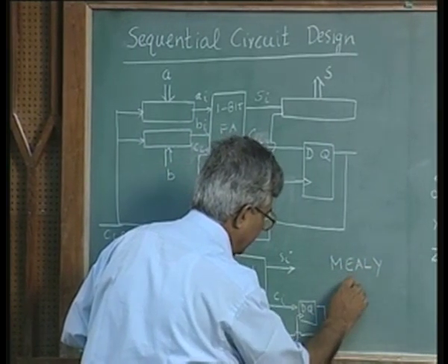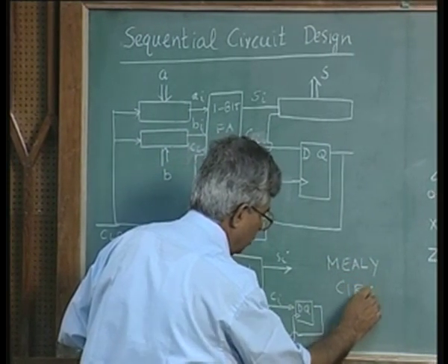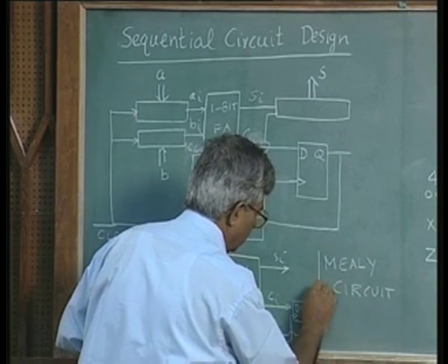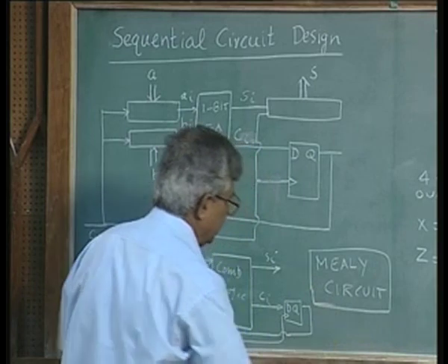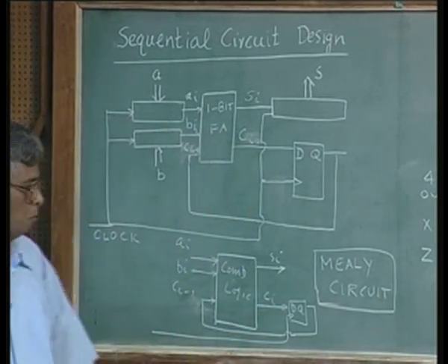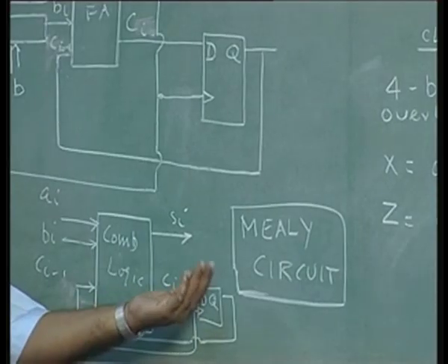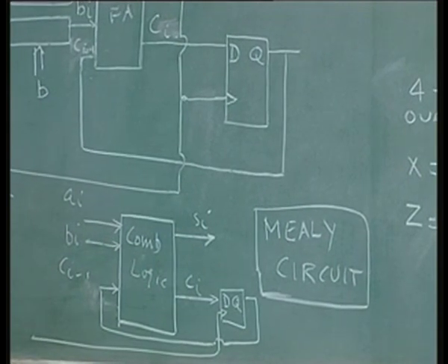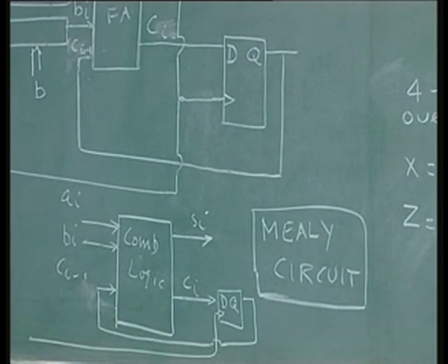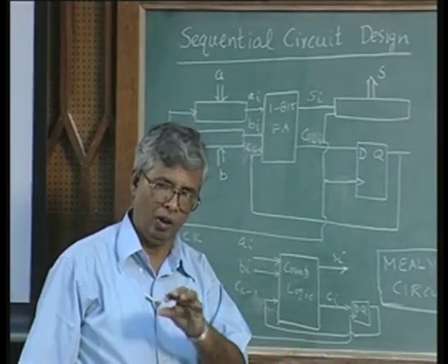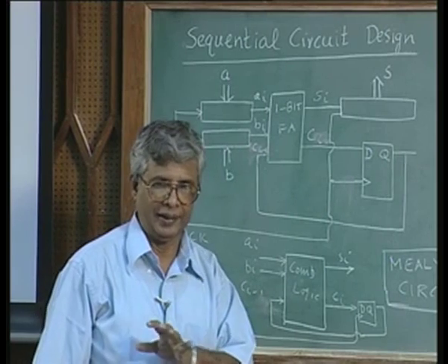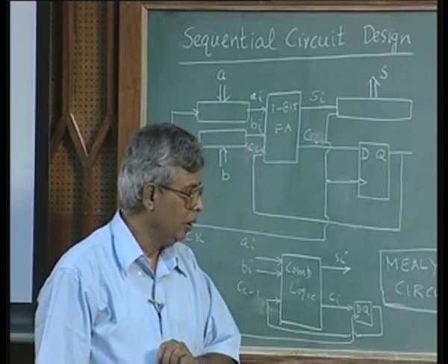So, in any circuit that you are designing, there is the possibility of designing it as a Mealy circuit or a Moore circuit. Mealy circuit is slightly easier to implement. Hardware wise it is slightly less complex. Moore's circuit is one which is slightly more involved in the hardware. Of course, it is not complex in the sense that it requires a little more hardware, but later on we